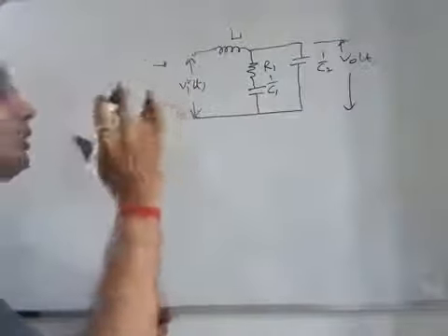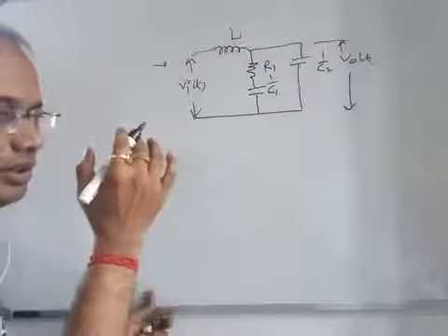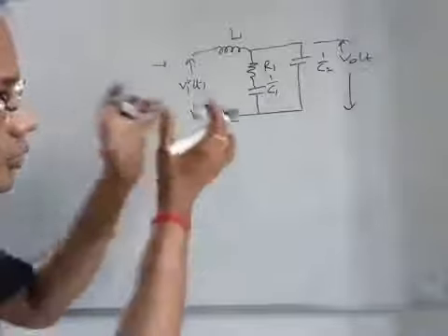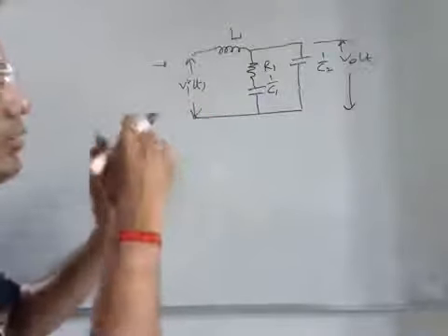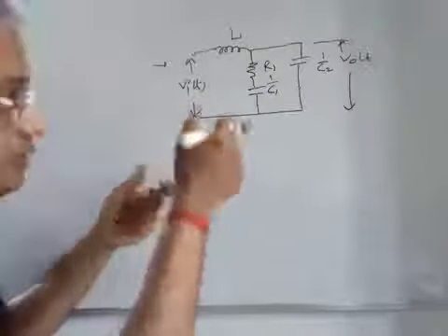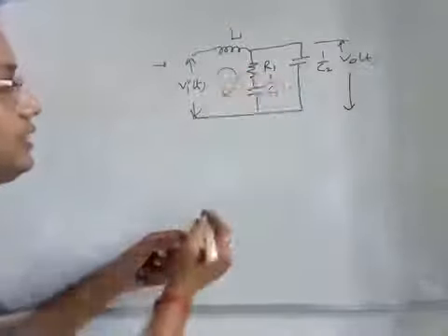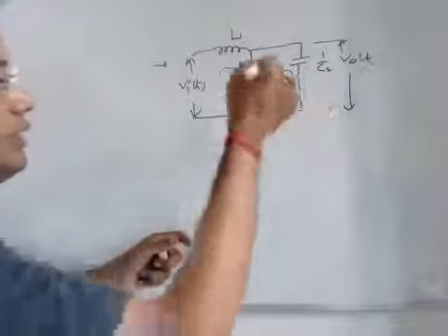By using mathematical modeling, you have to write the differential equation corresponding to the voltage drop or the current passing through the different paths. Here you can use mesh analysis. I can give you a hint. This is mesh analysis.